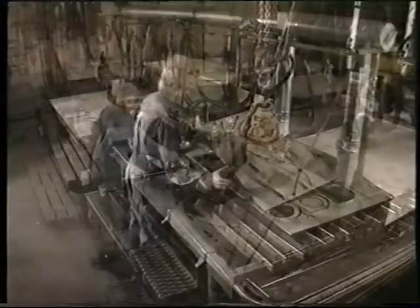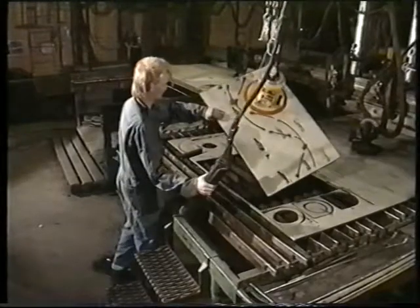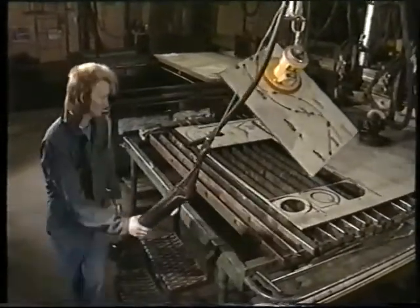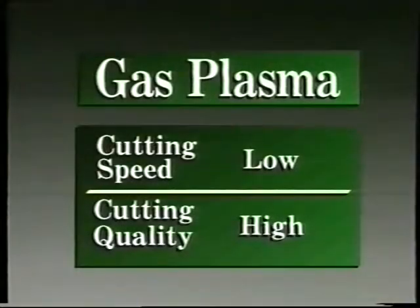Since many of the materials are non-magnetic, a suction lift is used in order to avoid expensive surface damage. Gas plasma gives you a low cutting speed, but has the advantage of high cut quality, in particular for the materials in question.